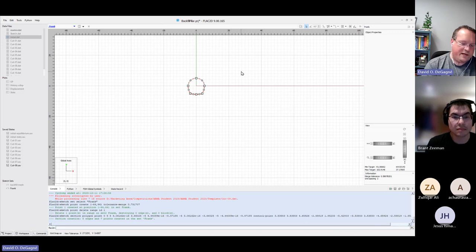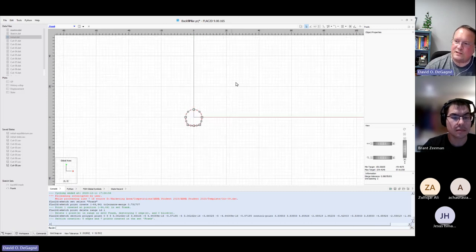Generally, when we have a gradation like that, we try to keep it at a 1:2 or 1:3 ratio. So you don't want to jump from a zone that's 1 meter to zones that are 5 meters. You can work your way up, going from 1 to 2 to 4 to 8. So sometimes there's a little pre-planning that goes into it.